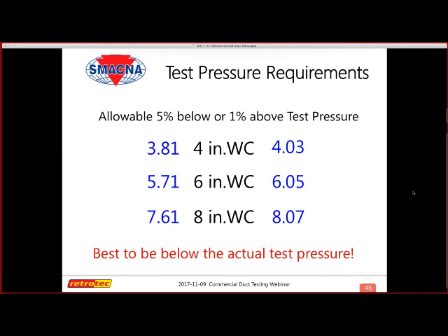So I can determine if you're going to fail your test, even if I don't reach a certain pressure that's required for the test. I can still determine pass or fail. And the one thing you can always determine is that you're failing. I can bring 5 more fans in here because your system is so leaky that I need 5 fans, and I can tell you failed. But the reality is I can tell you with 1 fan that you're failing, right? So that's one of the things that is key in terms of doing testing.